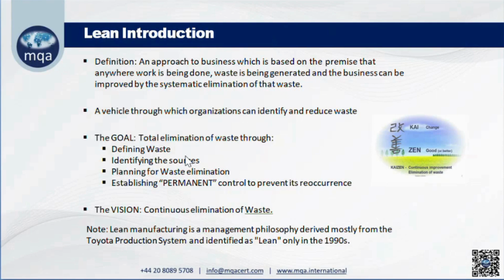How do we reduce the deviation? Between the lower and upper limits, how many deviations can fit? Three on either side means 6 deviations. So if the deviation itself is very large, then even a small further deviation means more defectives are produced.